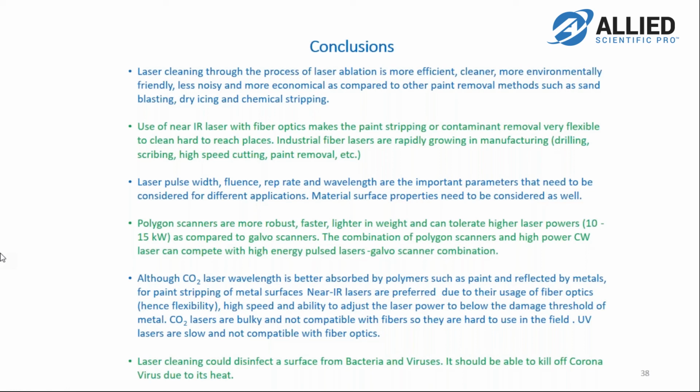So what are the conclusions? Laser cleaning through the process of laser ablation is definitely more efficient, cleaner for the environment, less noisy, more economical, and it's a good choice. Use of near IR lasers with fiber optics makes the paint stripping or contaminant removal very flexible to clean hard to reach places.